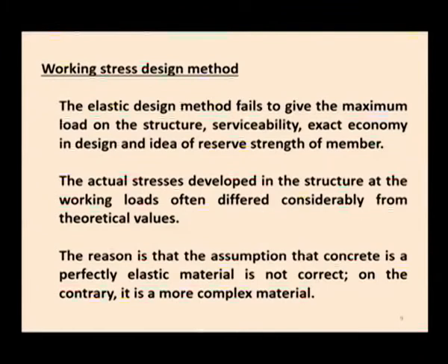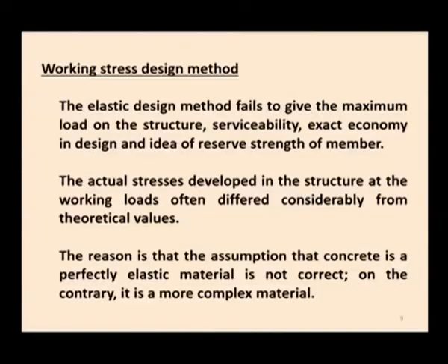However, deflection and cracking effects were not considered under working loads, working conditions in the case of the ultimate load design method. So, this method is only used to check the ultimate load on the structure after designing with the help of the working stress method, to give an idea of the real factor of safety of the structure. So, this is about the ultimate load design method.